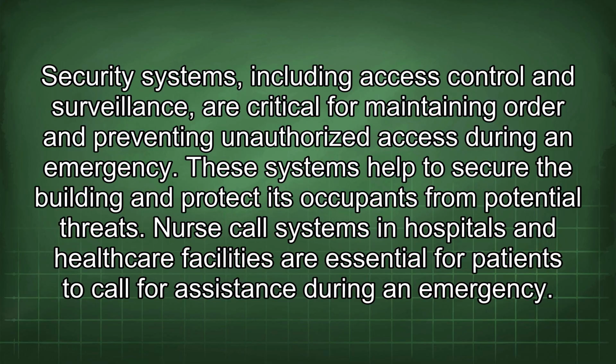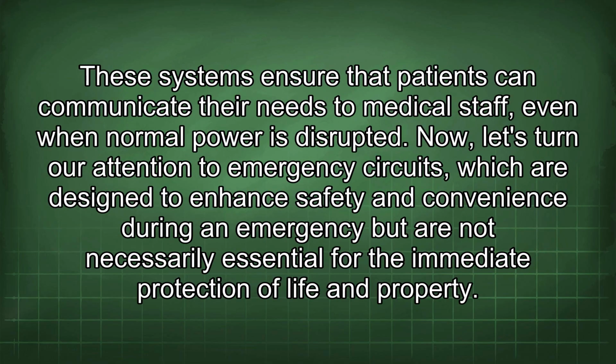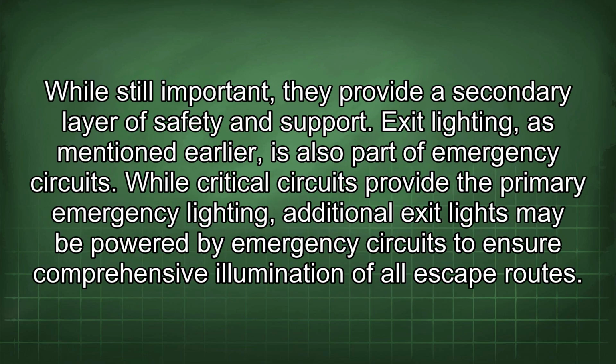Nurse call systems in hospitals and healthcare facilities are essential for patients to call for assistance during an emergency. These systems ensure that patients can communicate their needs to medical staff even when normal power is disrupted. Now, let's turn our attention to emergency circuits, which are designed to enhance safety and convenience during an emergency but are not necessarily essential for the immediate protection of life and property. While still important, they provide a secondary layer of safety and support.